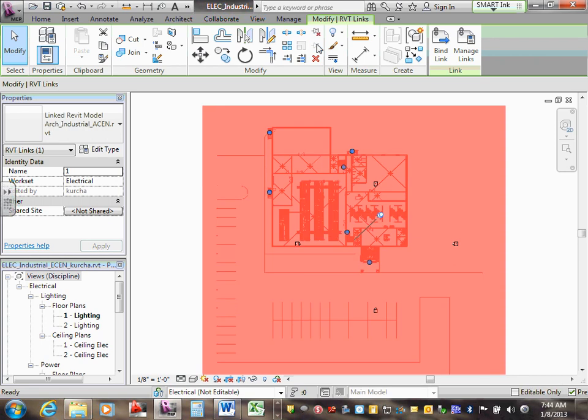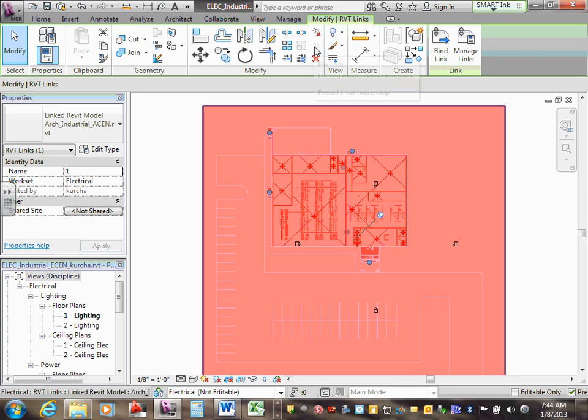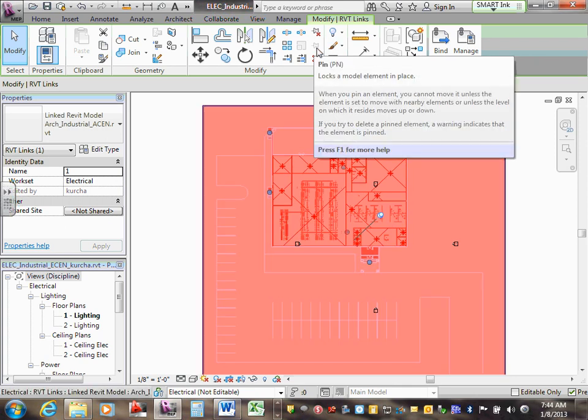What this will do, Kerry, is hold that building 3 model in place. So if you accidentally try to move the model and screw up your work, it will prevent it. Cool? Everybody got that one, guys? Red, and hit that button here. Gary says pin. It should turn gray. This means the building has been pinned.